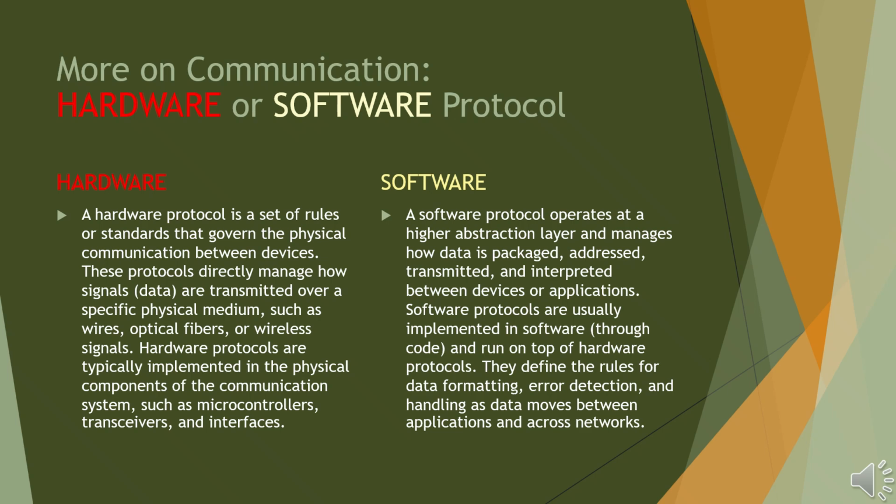and correction, using checksums, CRC, or parity bits to ensure data integrity; flow control and acknowledgement, making sure messages aren't lost or duplicated. For example, in UART, the hardware protocol defines TX/RX pins, voltage levels, and timing, while the software protocol defines data frames like start bit, 8 data bits, parity, stop bit.